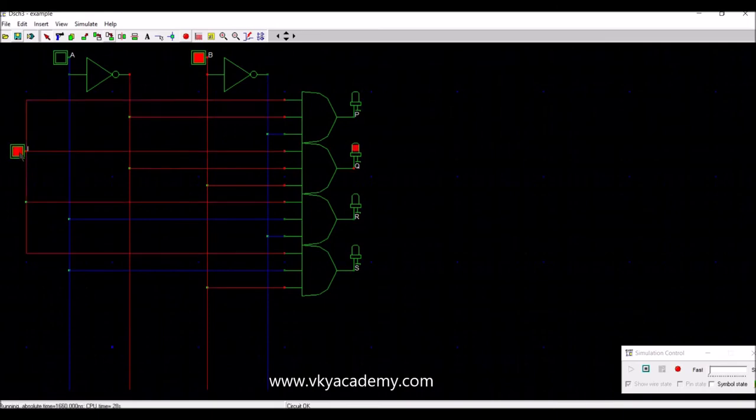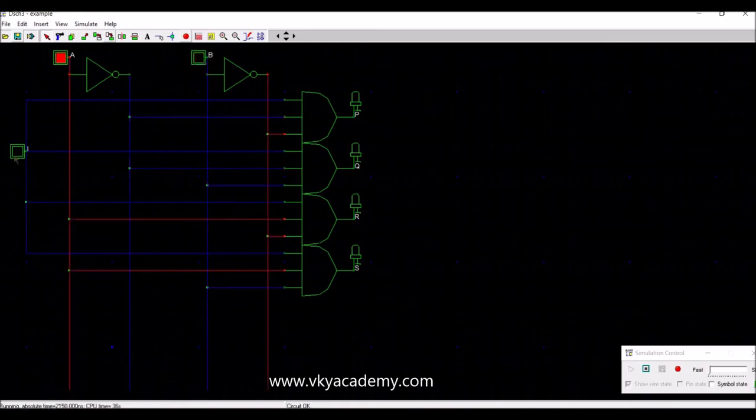The I input can be seen on Q output. Let us test the third condition 1, 0, and the input I can be seen on R output. And for the last selection line, it can be seen on S output. So in this way we can design a 1x4 demultiplexer as well. Thank you very much.